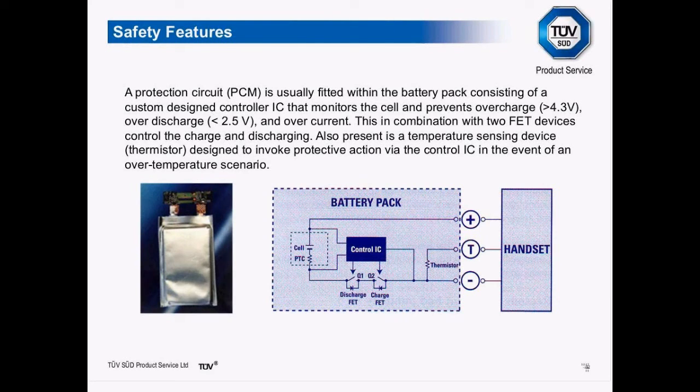For more complex systems that involve multi-cells, a more complex system is required, which is basically a battery management system, which may include communication protocols such as SM bus or CAN, which basically means there's data transfer between the pack and the end product to ensure that parameters such as overcharge and over-discharge are kept within limits. It also does things such as voltage sensing, so it monitors the voltage of individual cells within the battery pack to make sure they aren't excessively charged or discharged on an individual basis.